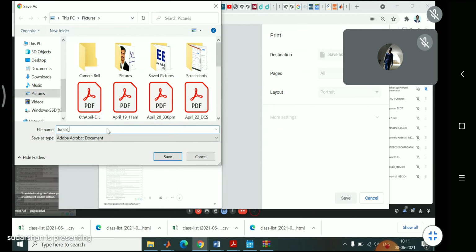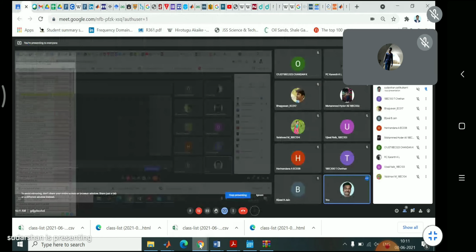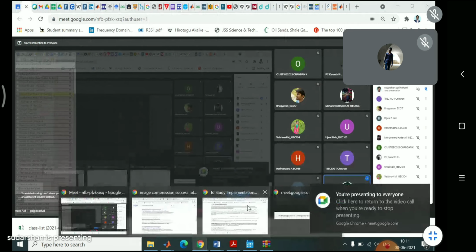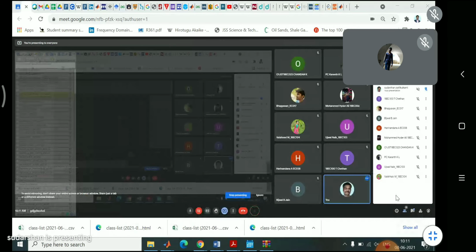Let us go for the second example. It will be a little more difficult because we add one more link and we go for the two link manipulator. So again, we can write the center of the first link is L1 by 2.